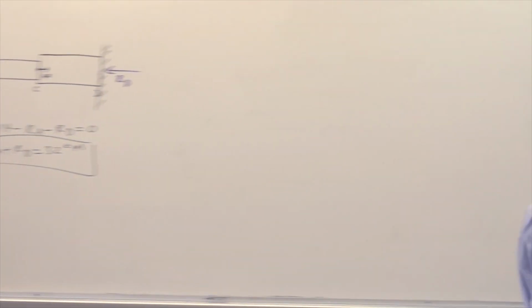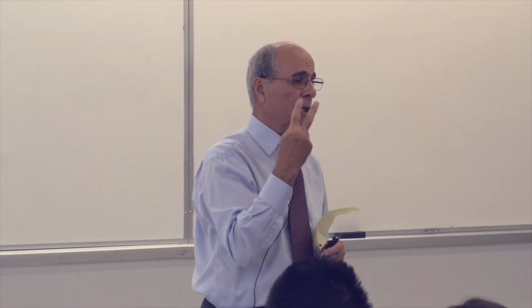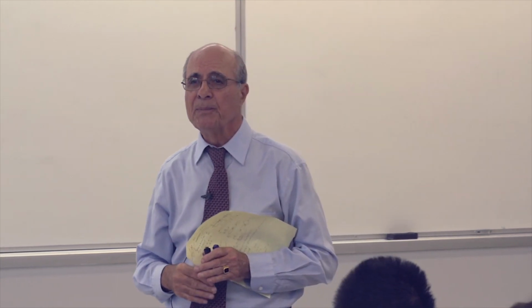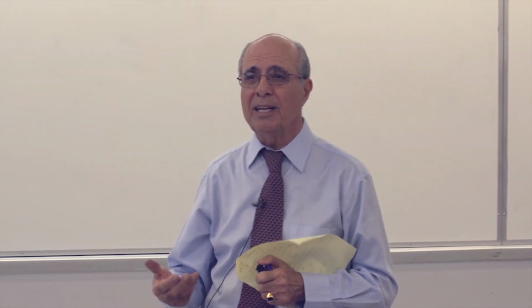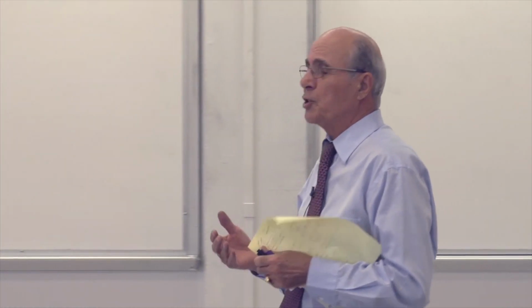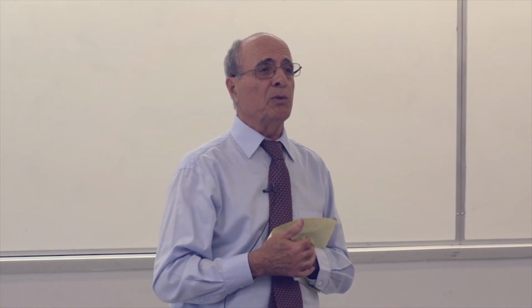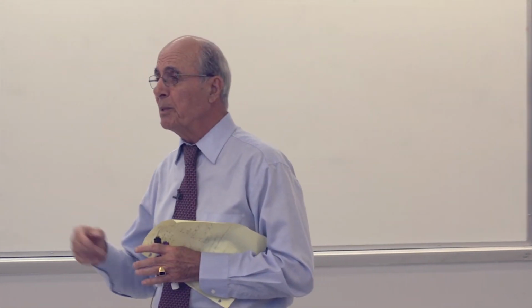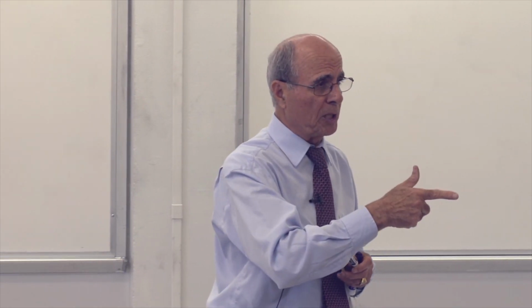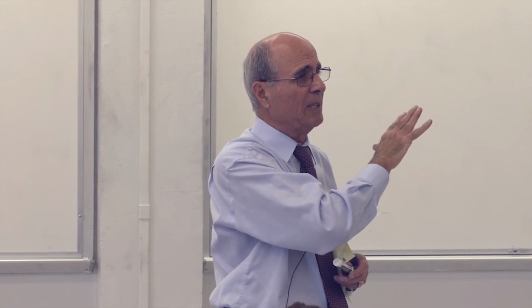So what do we end up with? We end up with one equation of static equilibrium, but two unknowns. How do we solve for R? What did I ask you to do last time? Bring the deformation into the system. What deformation? What's going to happen here? AB is going to change, yes or no? BC is going to go through the change. CD is going to go through the change. The first method that comes to your mind, there are two methods to use here. One is the general method, the other one is the superposition method. I already talked about superposition, so if I run out of time, you know how to do that. But I will explain it anyway, don't panic.